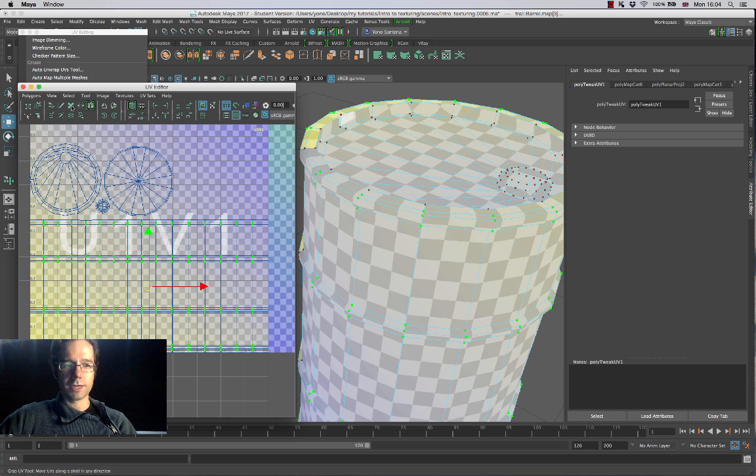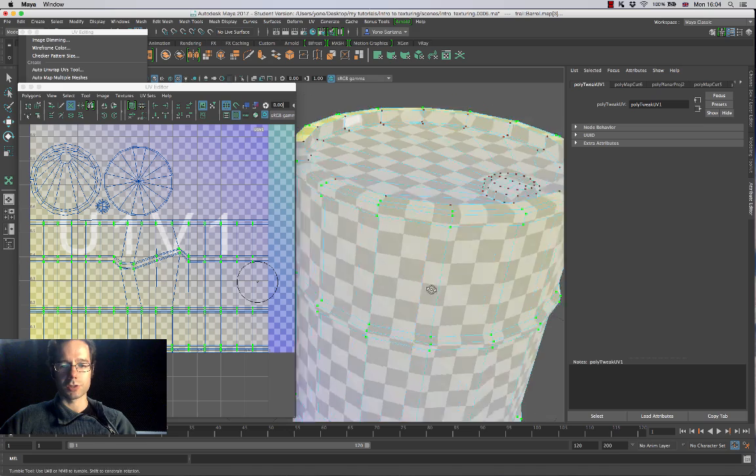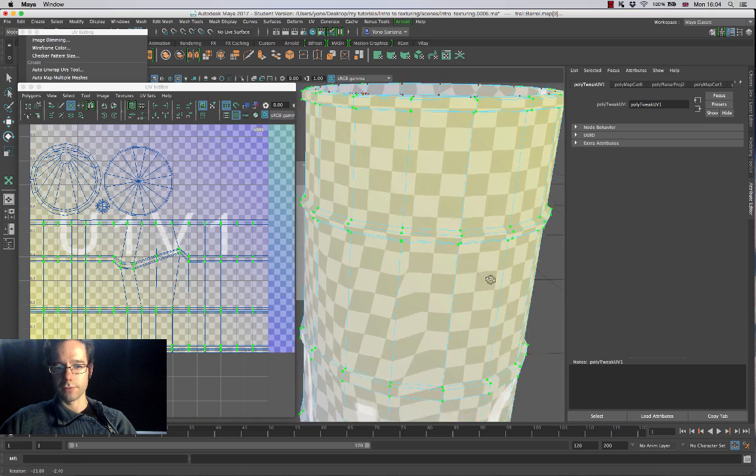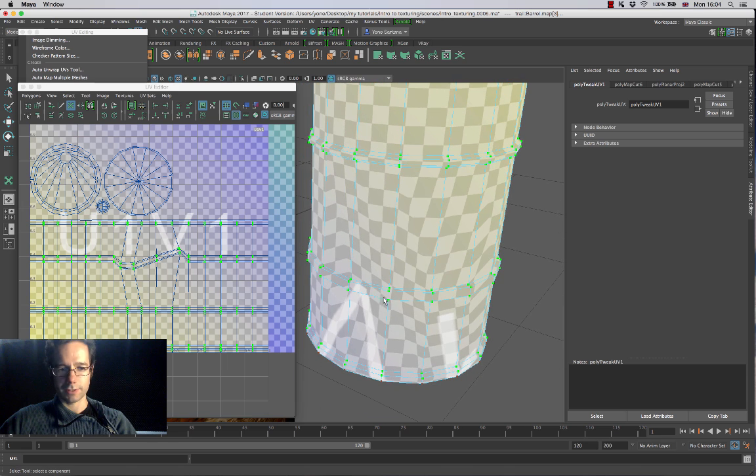For example, if I just made a little mistake and pushed this Move tool over here, I get a little brush like the same tools that we've been using in Maya before, and I can use the B key to change the size of the brush that I'm working with, and you'll see that I'll be able to move things around in space like this. This is very handy for us to make little changes, but you're going to see that it's going to radically warp the look of my UVs. Oh, there it is down there. That's where my pinching is happening, as you can see.